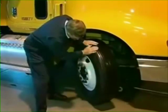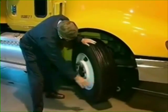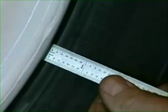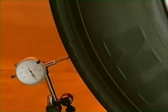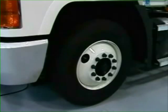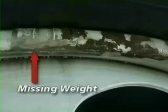For vibrations felt in the steering wheel, start by inspecting the front tire and wheel assemblies for the following: correct seating of the tire on the wheel, excess runout of the tire wheel assembly, and the tire and wheel assembly being balanced. Look for indications of missing tire weights.